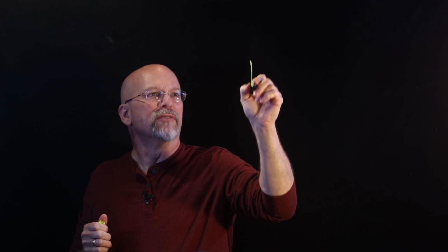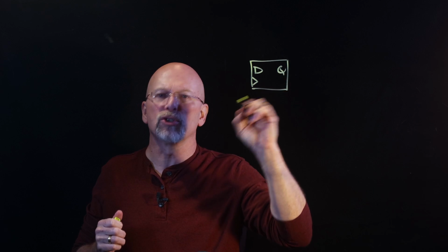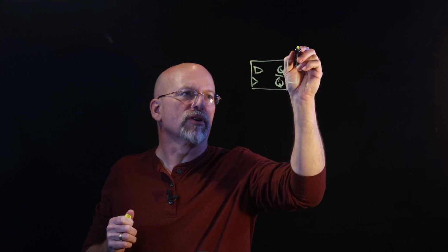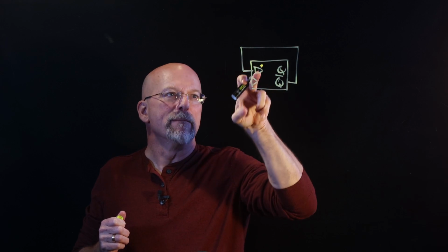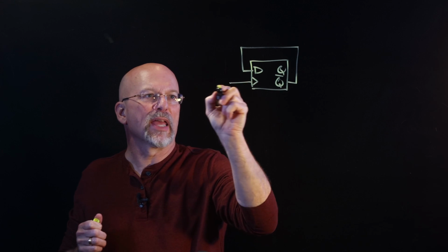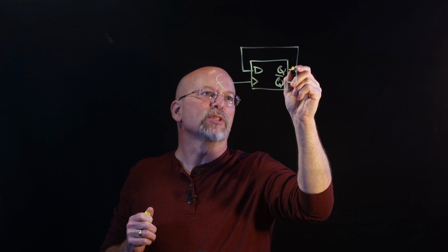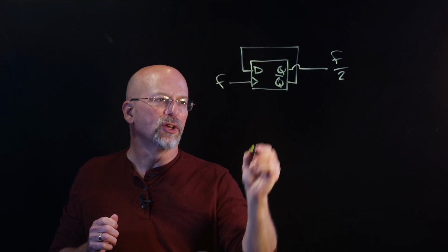The circuit we're going to start with is a divide by 5 circuit. Now, if you go through our computer organization videos, you should see this divide by 2 circuit, where what we did was we took the inverse of what was stored inside the box, made that go into D, and if we had some sort of a clock frequency F that went into this circuit, then what was coming out of Q was a frequency divided by 2.